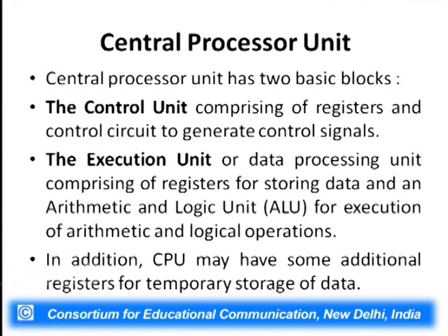For example, an 8-bit computer processor will have an ALU which is able to work on 8-bit data. Similarly, for 16-bit data, it will be a 16-bit ALU and so on. And it performs the logical operations also. By logical operations, we mean AND operation, OR operation, XOR operation, NOT operation and so on.